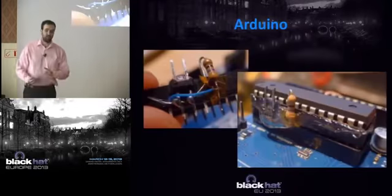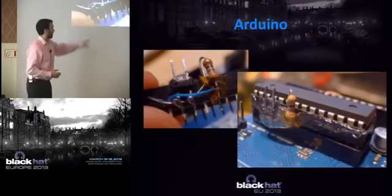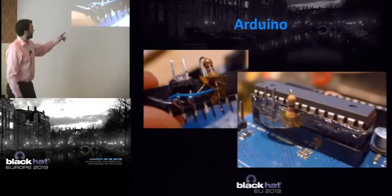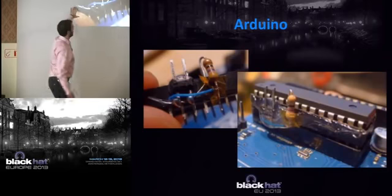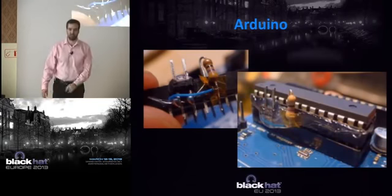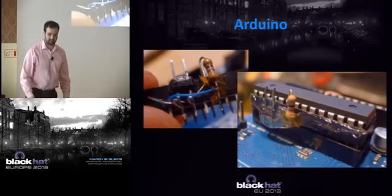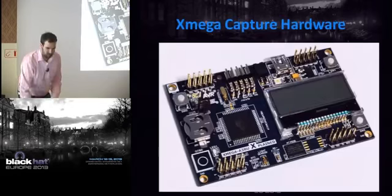You can even use an Arduino as a target. It is an AVR. It's almost the same AVR I'm showing here. And I've sort of hacked together a DIP socket with a resistor in one of the power lines. And then that resistor you connect up to your scope. So that's a sort of very low cost type target.